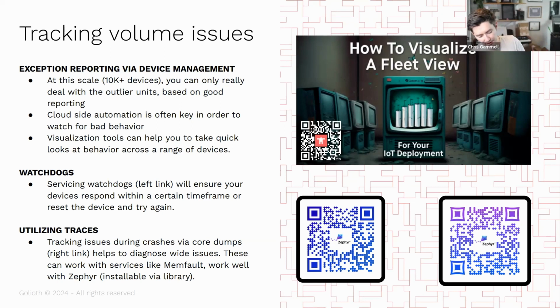Another thing though is you need the devices to take care of their own. And one way you can do that is using watchdogs. This link on the left here is just the Zephyr docs on watchdogs, but software watchdogs, hardware watchdogs, these are all capabilities to make sure that if the device is not operating within its limits, it will reset itself at the very least, or call for help, or have some kind of exception reporting either on the device or on the cloud.